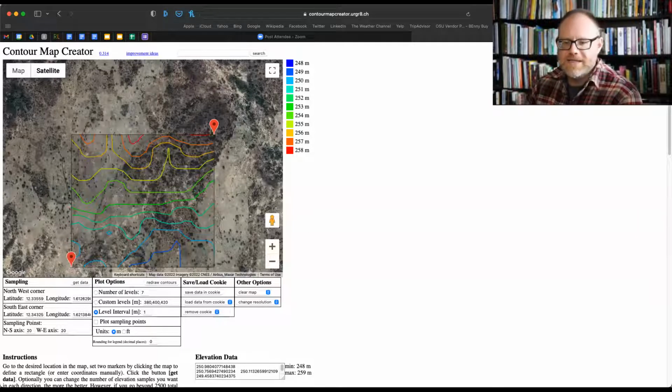And as we've talked about before, let's say your property boundary is something like this. In terms of tracing those contour lines, what we would do is pick a nondescript color, usually a light gray works really well, or something that the eye can ignore. And what we'll do is trace this in Google Slides. And notice that I'm tracing off the property boundary, because what you'll want to do afterwards is label the elevations, but it's really important to label them off the property boundary.